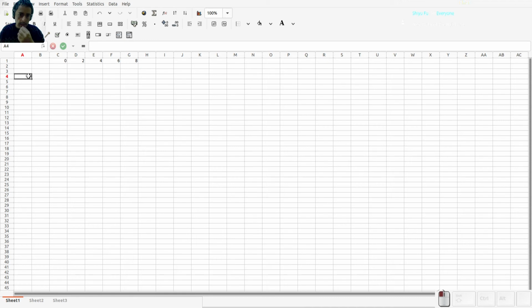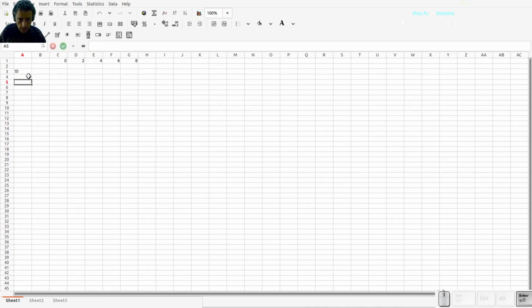We know that at time 0, what is the excess pore water pressure that we have? We said it was 10 kPa uniformly over depth. So at time 0 I have 10 kPa uniformly distributed with depth.